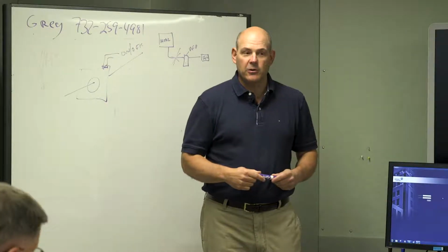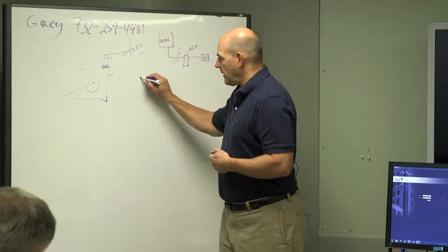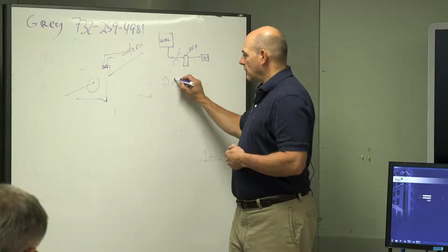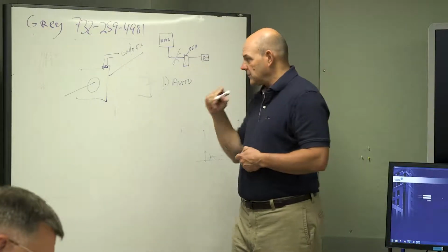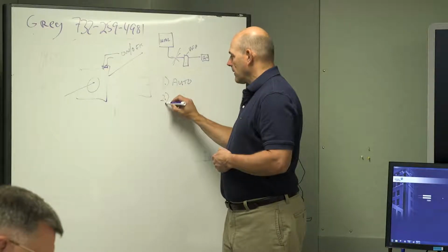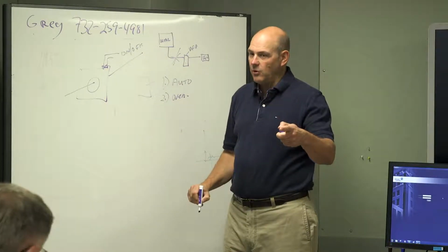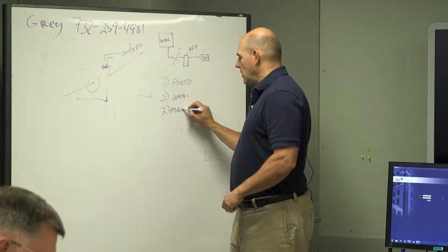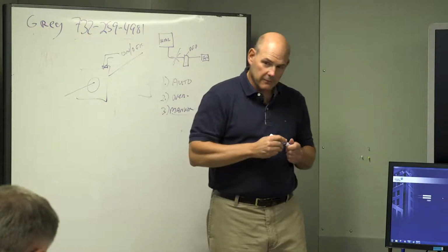So when you have a VFD, this is going on a little bit of a tangent. When you have a VFD, there's 3 methods of control, all right? One is auto via those 3 points. Two is manual override from the front end. And 3 is manual, going to the drive. And that stuff will be covered when we walk around in the field.